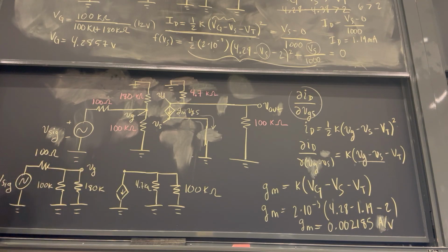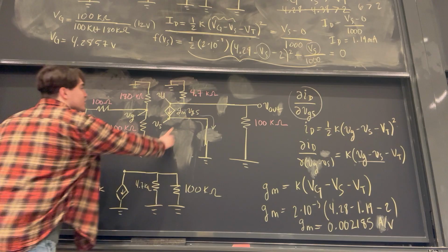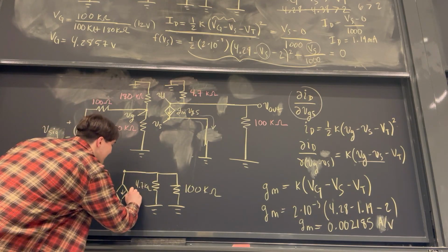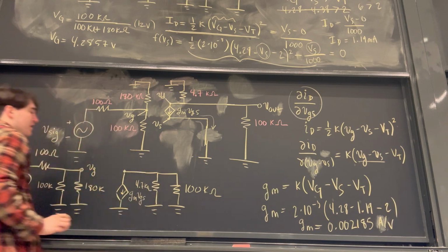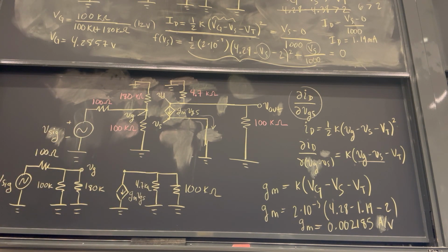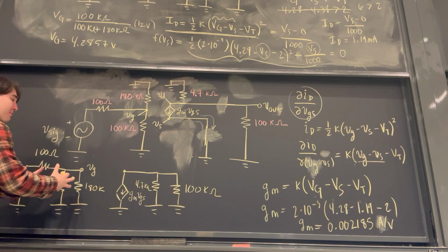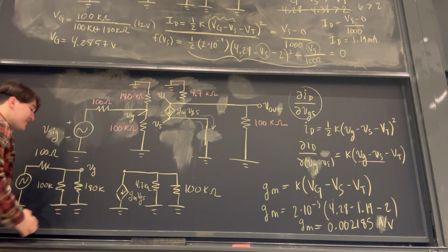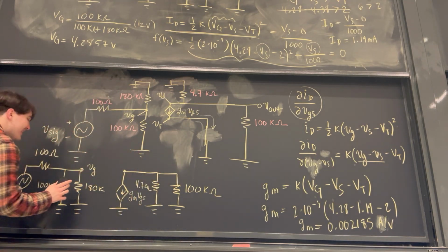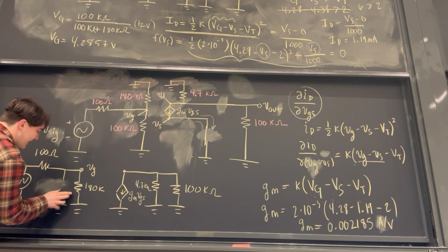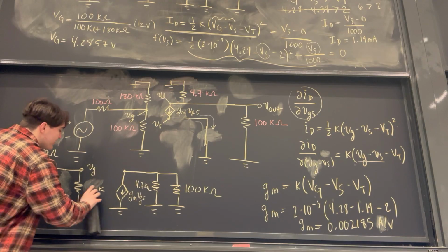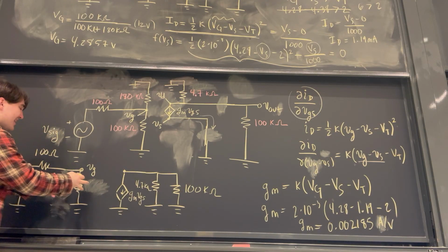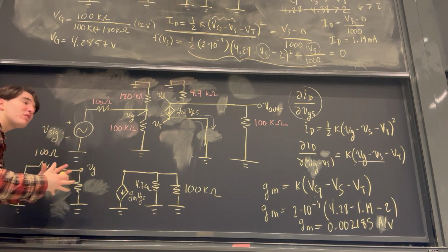So if you take a look at this simple circuit, it is so simple to understand. It's just two simple little resistor circuits. And then we also need to remember that this current source here is gm times VGS. The last thing I want to note is, let's combine these parallel resistors into single resistors. That makes it even easier. We can get rid of these double parallel resistors and turn it into one resistor equal to the equivalent of both of the resistors in parallel.